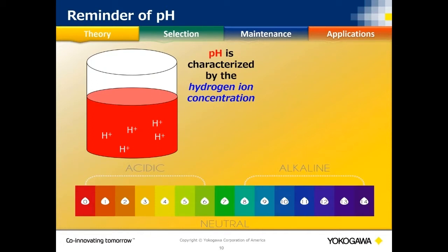So it will actually be affected with hydrogen activity going on as well. So sometimes there's applications where if your pH changes, your hydrogen ion concentration changes, you're going to see that in your ORP value as well, and we may have to compensate. So we'll talk about that in a little bit more detail, what we call pH-Compensated ORP.